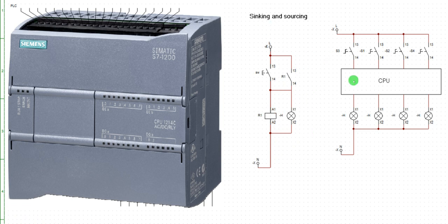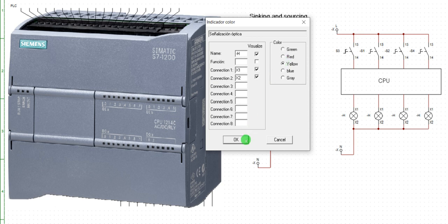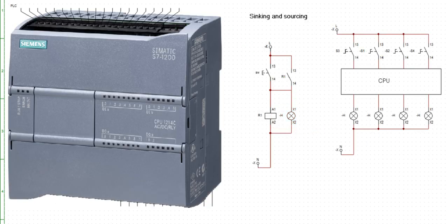Okay, now let's simulate this. Now I want to put on this lamp, right? Now watch this one. This is a momentary switch. It does not maintain. This is a spring loaded switch, a spring return switch. It does not maintain. Once you activate it, it will click and return back. Okay, let me change this lamp to yellow. Just look at the function of this switch. Once it closes and you take off your finger, it will bounce back to its original state. So it just momentarily flashes and goes back, flashes and goes back.